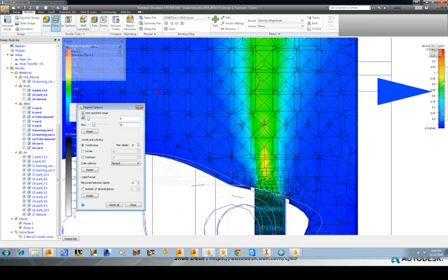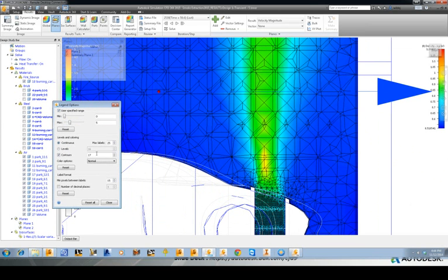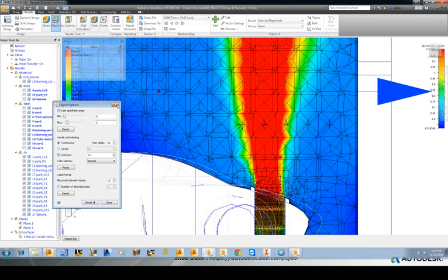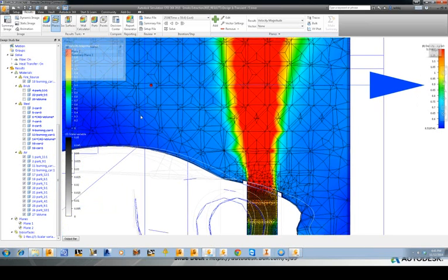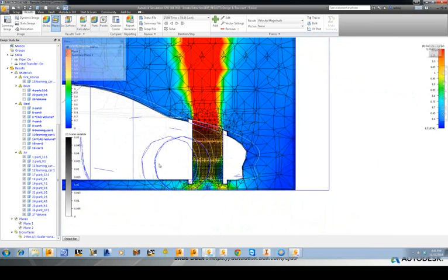In terms of whether we have enough, that's always hard to find when it comes to CFD. Normally, when it comes to these kinds of plumes with fires, I generally try to overmesh. You can see how tight the mesh is in the actual fire zone itself. That is mostly due to all the heat that's being pumped out of that fire. So trying to get enough mesh in there so that it's very stable, as a lot of times there's a transient heat up curve that people like to plot here. And more mesh usually helps.